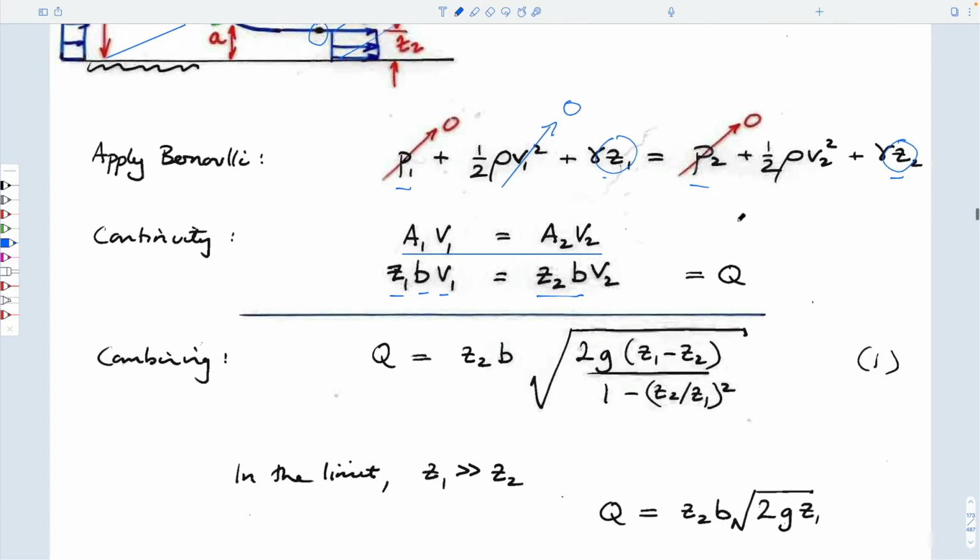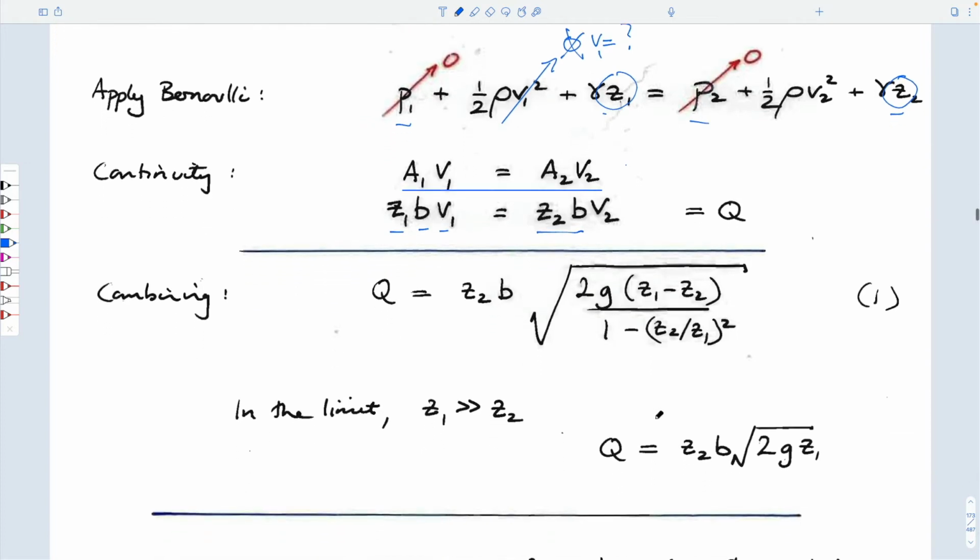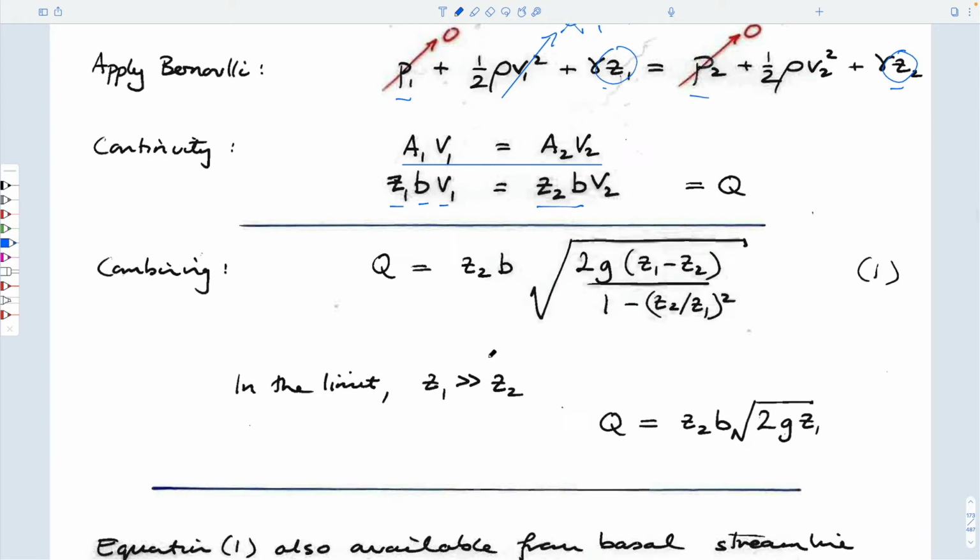And so we can just substitute into Bernoulli. We don't really need to do it this time in terms of this velocity. Well, I guess this is actually done not assuming this. So we haven't restricted by that assumption. We've linked it in these ways, and you can tell it because this would be the difference in pressure upstream to downstream, and this would be the difference in areas upstream and downstream, just like it was in the Venturi equation. And it works out to be this.